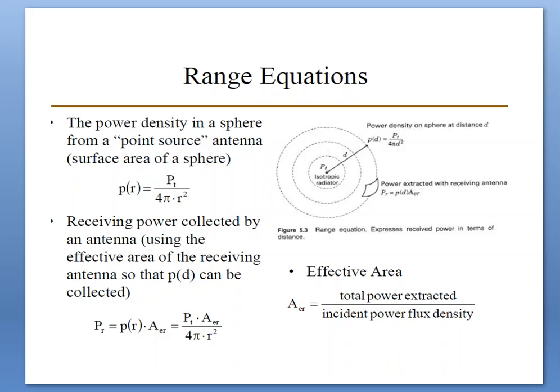There are two types of RF sources we have. One is directional sources, the second is omnidirectional sources. Directional sources, such as a directional antenna, propagate the radiation beam in a specific direction, but omnidirectional sources spread the field in all directions, that is 360 degrees, with 4 pi steradians, such as ideal sources called isotropic radiators.